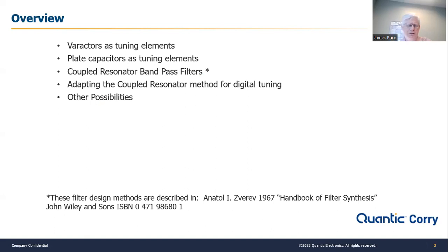It goes through the design techniques that you'd want to use for a coupled resonator style filter, which is maybe a little bit different than the typical lookup tables for filters that most people are familiar with. The reason you would use these is because they particularly lend themselves to using varactors and variable capacitors to tune the filters.